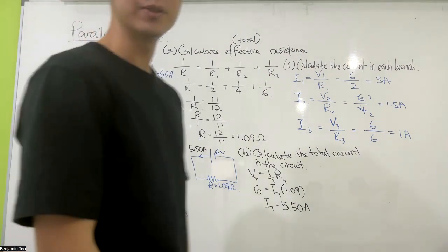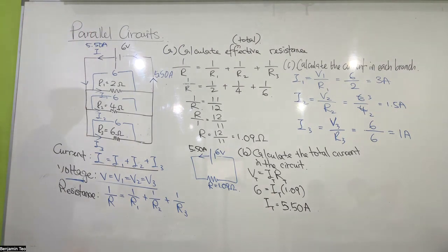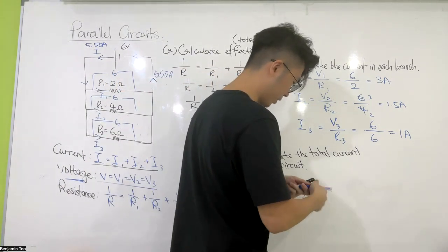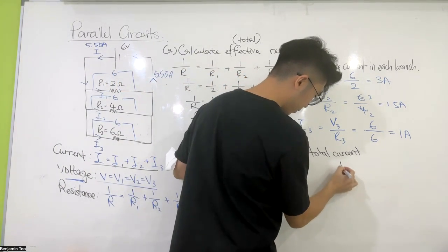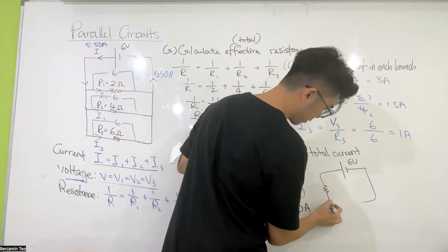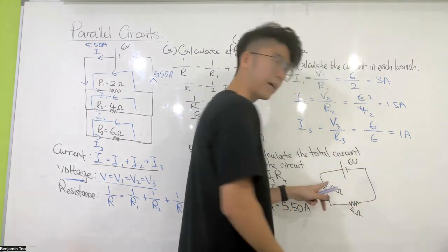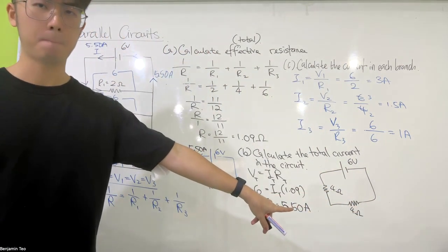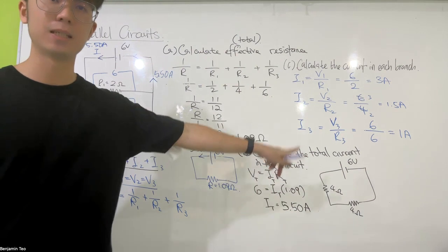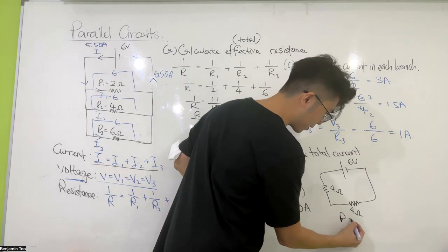Right, so those are the two types of circuits you have. Which one is better? What do you think? Series or parallel is better? See, if I do one series, 6 volt, I put 2 resistors, 4 ohm and 4 ohm. What is my effective resistance? Effective means total. What is my total resistance in that A, right? So you just add it. With the series we just add. So total resistance is 8 ohm.